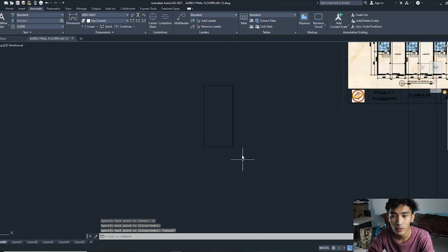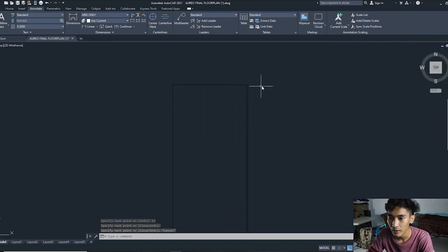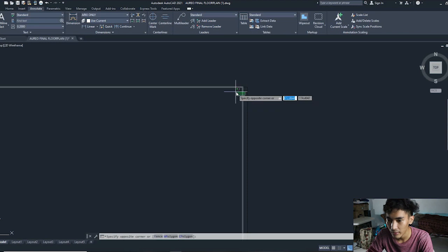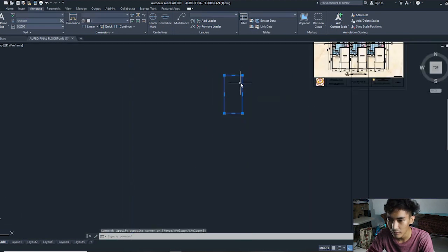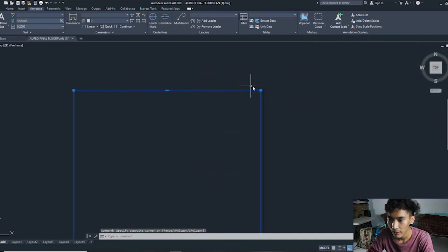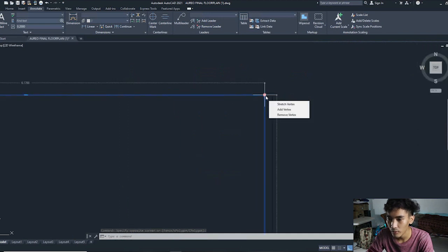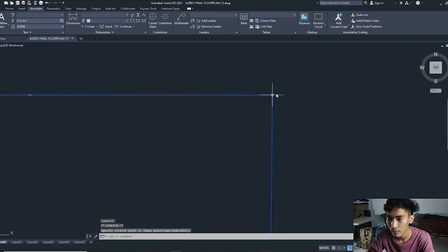So in order for you to save a lot of time in not manually making the walls, the thing that you should do is select your rectangle, then move the endpoint to the right where you extended. So move there, left click, then left click again.